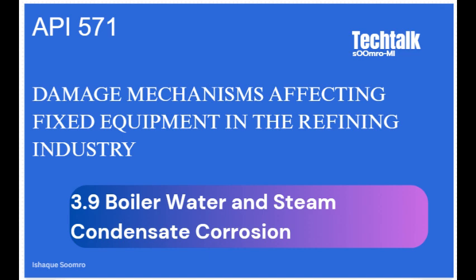Our source material is very focused. It's about mechanical integrity, identifying the three main drivers of damage: dissolved oxygen, O2, carbon dioxide, CO2, and the one that, well, often catches people by surprise, flow accelerated corrosion, FAC. So our mission today is pretty straightforward. Give you, the listener, the shortcut to understanding this pretty complex chemistry. We're going to break down the critical factors, pH, temperature, gas levels, and lay out the protective measures needed to keep these huge systems running safely. Basically, if you need the quick version to sound smart on boiler integrity, this is it.